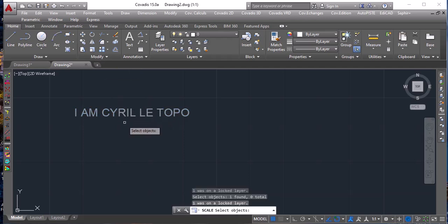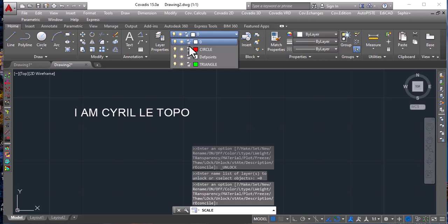Once an element shows this, it does not allow us to modify it because this layer has been blocked. So we are going to deactivate or unblock. We come to the layer, and on this key, we unlock. Make sure we have unlocked this key. It's unlocked now.